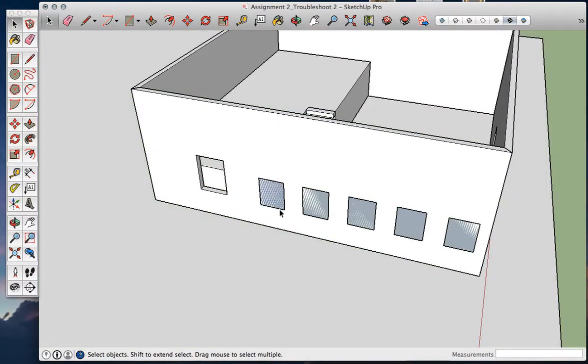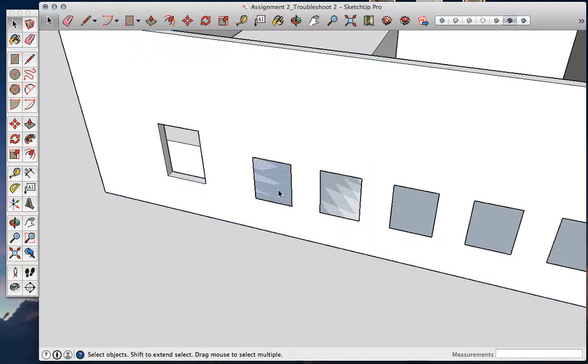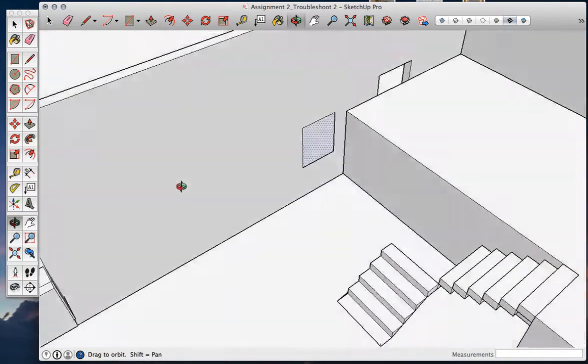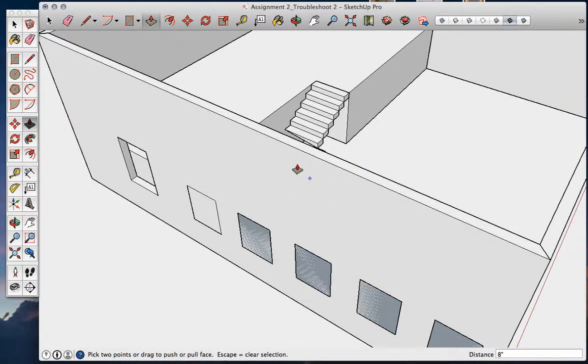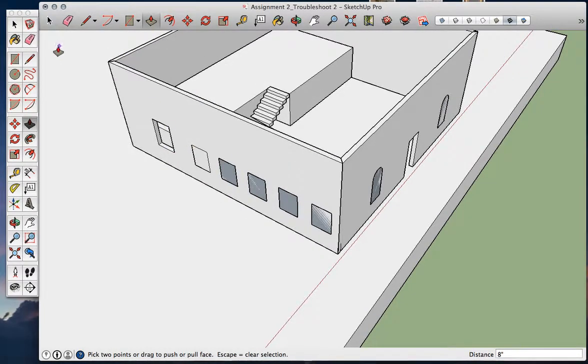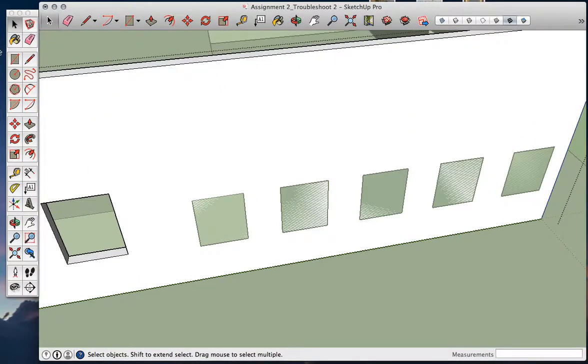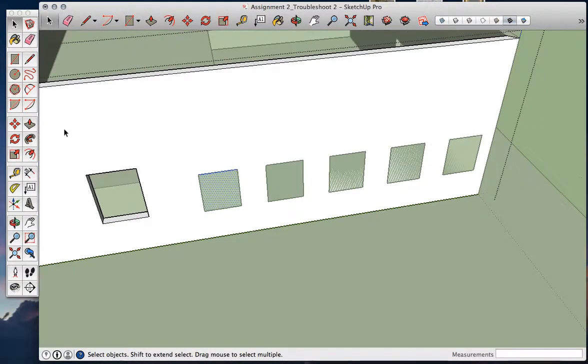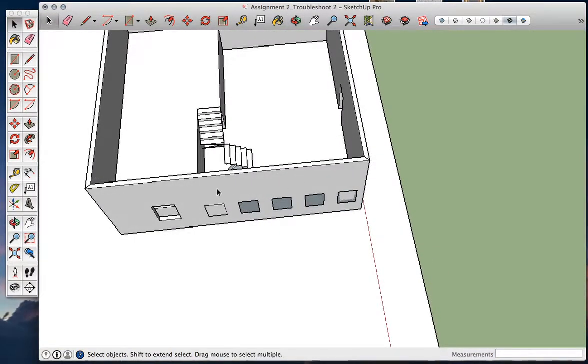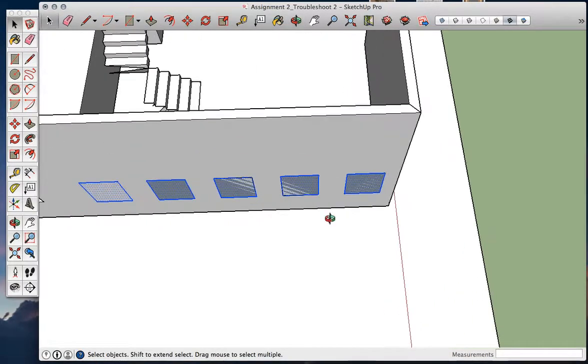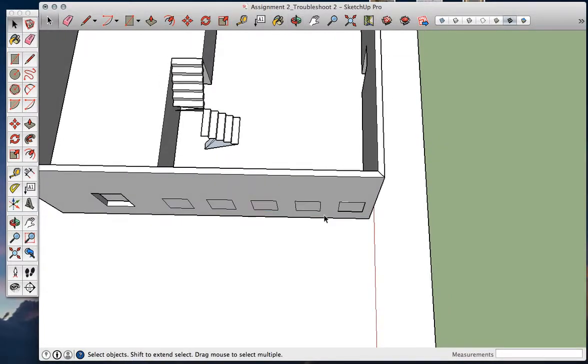These openings here are sitting on top of this closed group. So if I try to push-pull this through, it's going to push-pull through, but what's happening is I've got now a solid sitting on top of and through another solid. So the best way to handle this would be to open this up, go ahead and make a rectangle where that other rectangle is. If I want, I can double click on that and go to my move tool and hit my copy button and make a copy from one to the next, and then times 4, because there's 4 more rectangles. And then I'm going to close that group, select this stuff that's sitting on top using my drag method from left to right, and then delete that because I don't need those anymore.